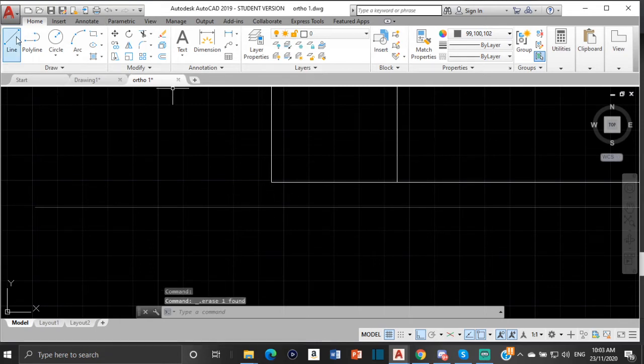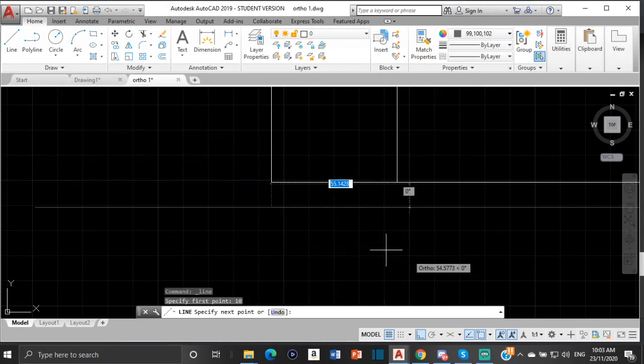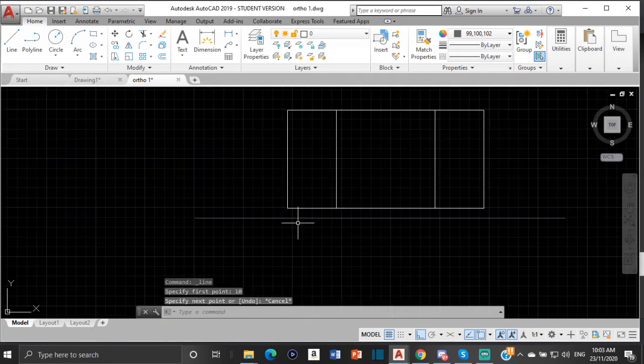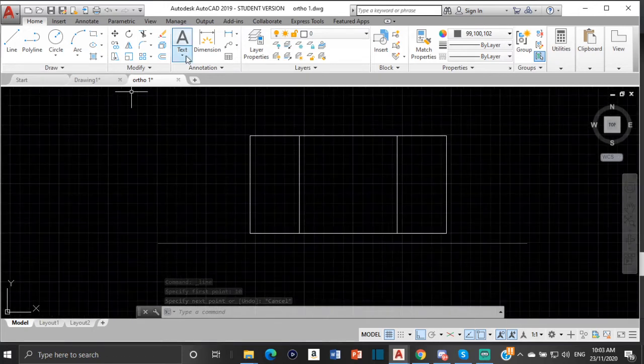No, I didn't have to draw this line down here. I could have just put my cursor here and then moved my cursor down and typed 10 without clicking anything, and then I could start drawing my line from there. So I didn't have to draw that little piece of the line. So I have my XY line. I'm just going to label that line XY.